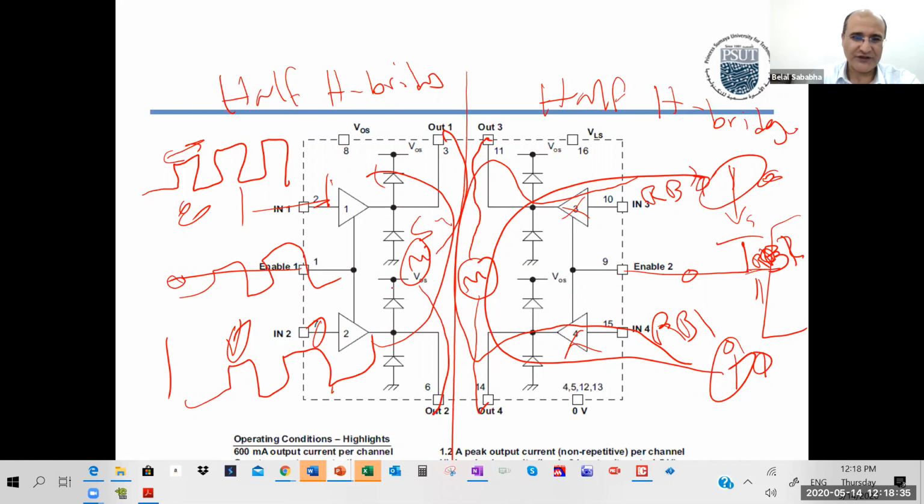these 1s and 0s will control the direction, right? And the enable will control the speed, on, off, on, off. So you can have 1 PWM signal instead of 2, one here and one here. But in this setup, we use half of the H bridge to control the speed, or controlling on and off a motor, replacing what we did before with using 1 switch.